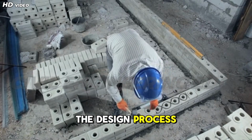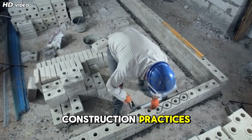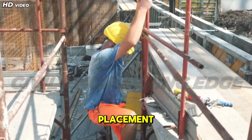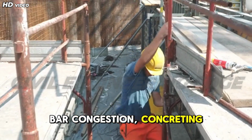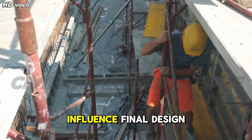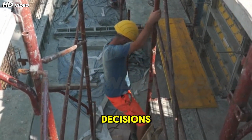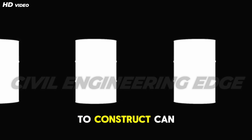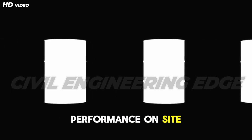The design process also considers construction practices. Practical aspects such as reinforcement placement, bar congestion, concreting quality, and workmanship influence final design decisions. A design that is theoretically sound but impractical to construct can lead to poor performance on site.